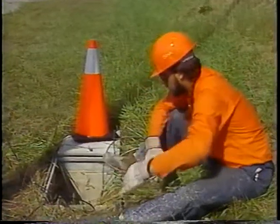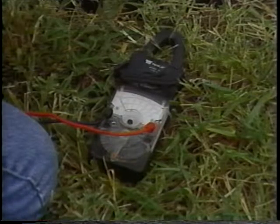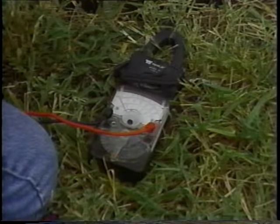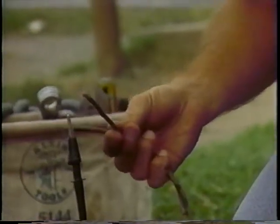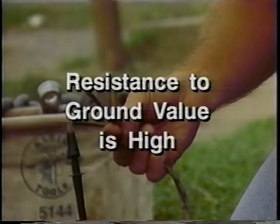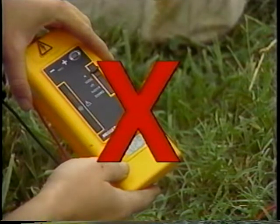Each cable should be identified by lane or by probe. Then, using a volt-ohm meter, check that the series resistance or continuity of the probe and the cable is within 10% of the calculated value. To ensure that there are no breaks in the probes or wire insulation, you should also check that the resistance to ground value is high. Do not, however, use a megger to check this resistance because the high induced voltage will destroy the probe.